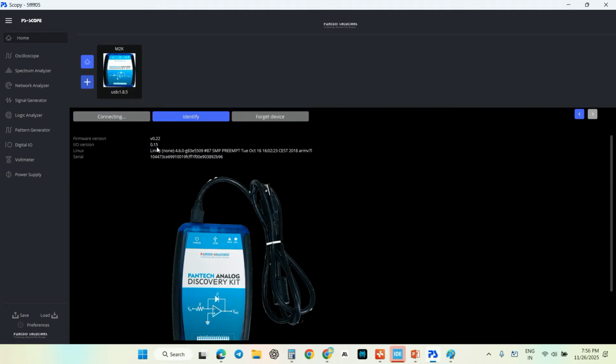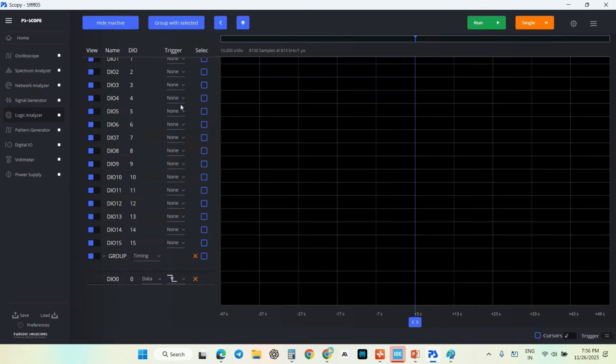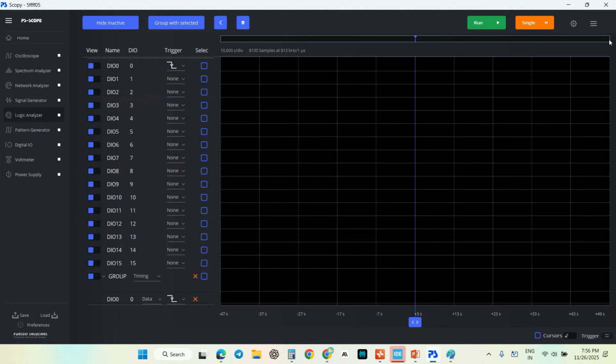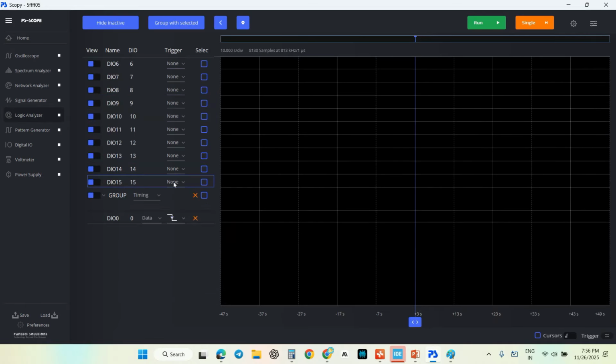So we just wait for some time. It just needs to connect. Okay, it got connected. After it got connected, I'm selecting one data channel. Here I select what clock pulse it is, whether it starts from low or high, and what mode I'm going to use. Whenever I'm using some other protocol for debugging, to check whether the data is properly sending or not, you select your protocols. And here I'm going to be measuring my time.